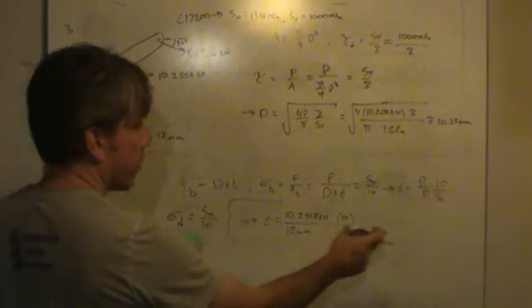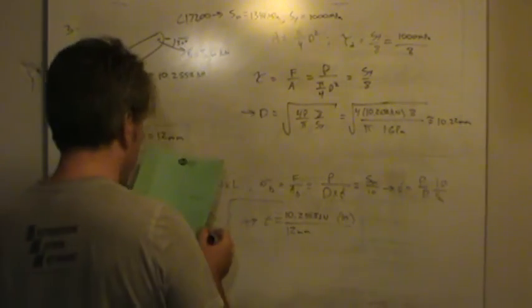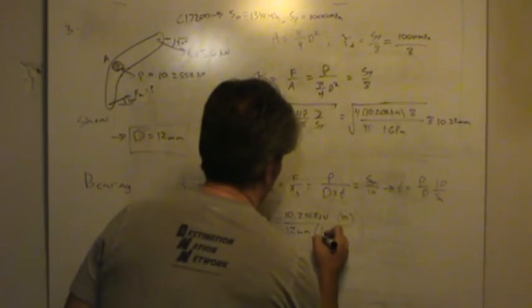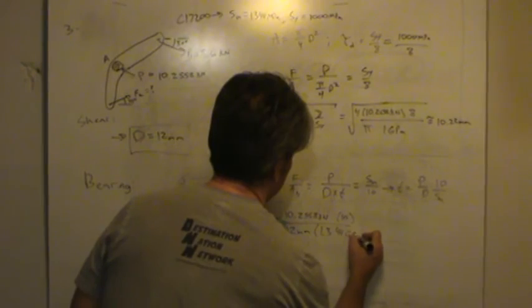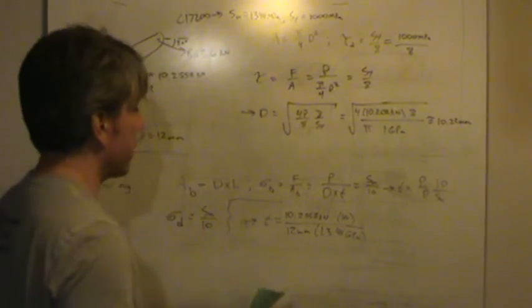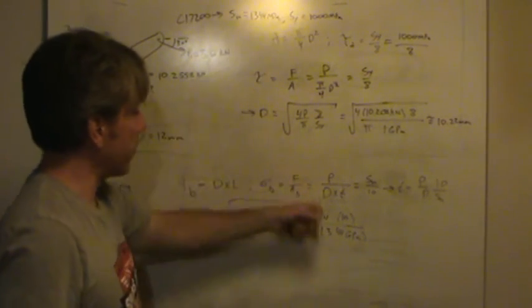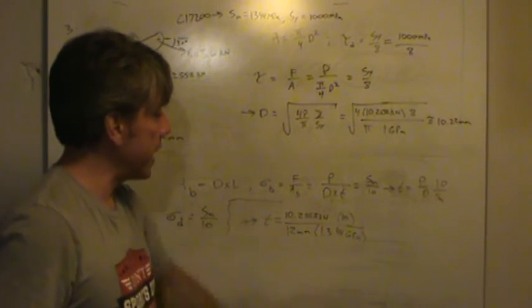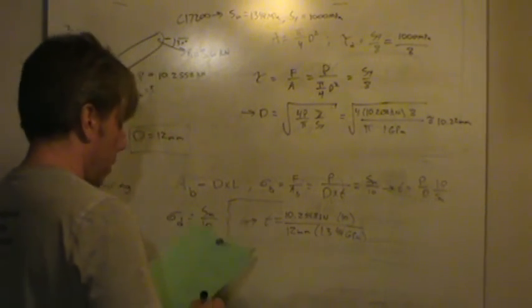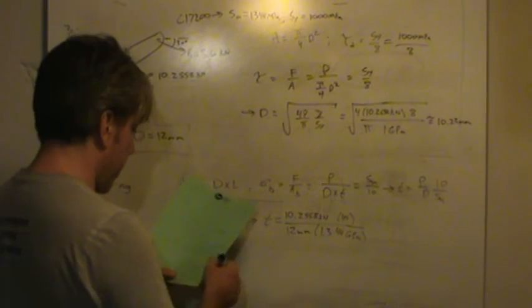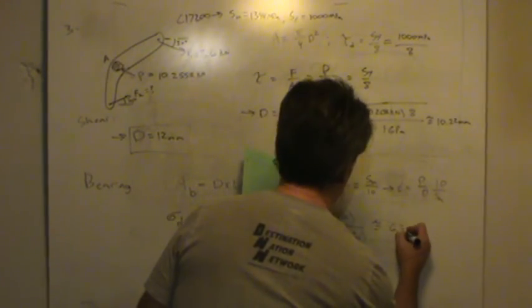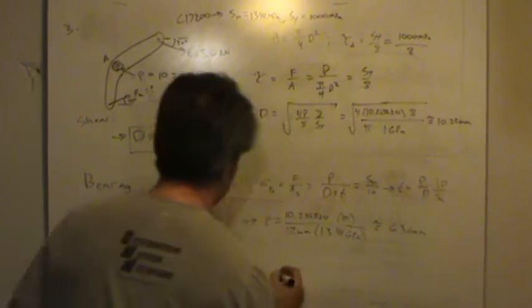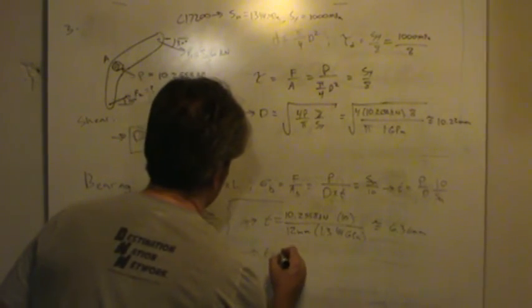And divided by the ultimate strength, which is 1.344 gigapascals. Again, I'm just converting to gigapascals immediately instead of megapascals so that it plays nicely with kilonewtons. Okay? And of course we'll end up with a thickness in millimeters. When you plug this in your calculator, you get about 6.36 millimeters. So I went ahead and specified a thickness of 7 millimeters.